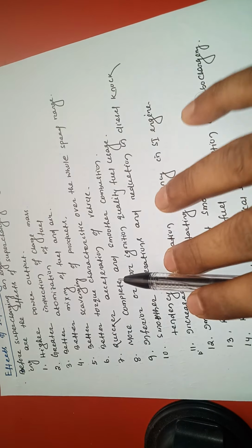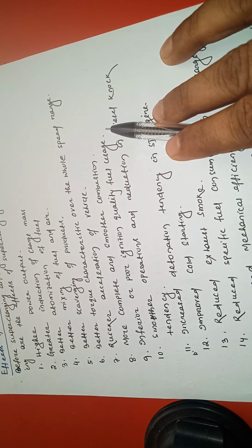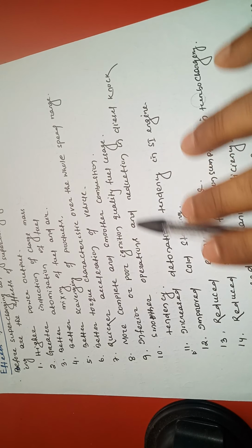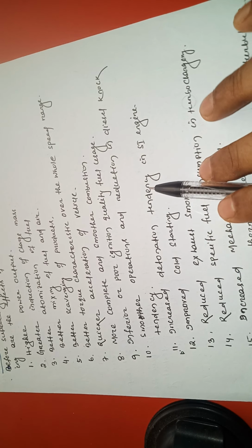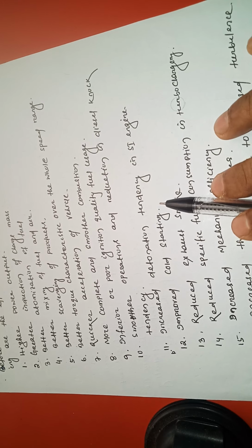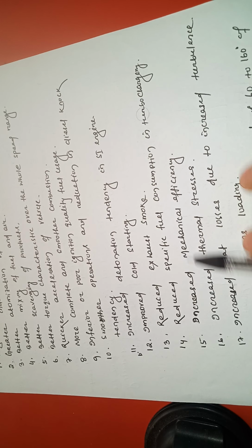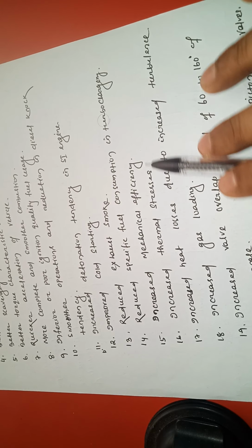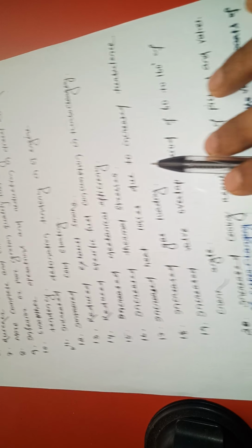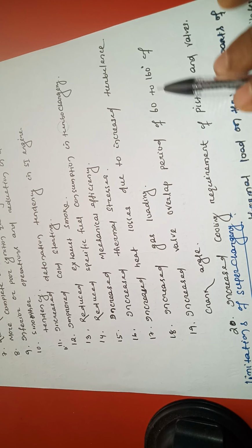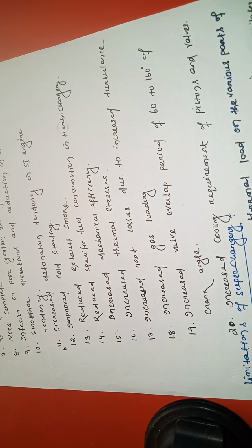of vehicle, more complete and smooth combustion, use of inferior or poor ignition quality fuel, smoother operation and reduction in diesel knock tendency, increased detonation tendency in SI engine, improved cold starting, reduced exhaust smoke, reduced specific fuel consumption in turbocharging, increased mechanical efficiency, increased thermal stress, increased heat losses due to increased turbulence, increased gas loading, increased valve overlap period of 60 to 160 degrees of crank angle, increased cooling requirement of piston and valves.